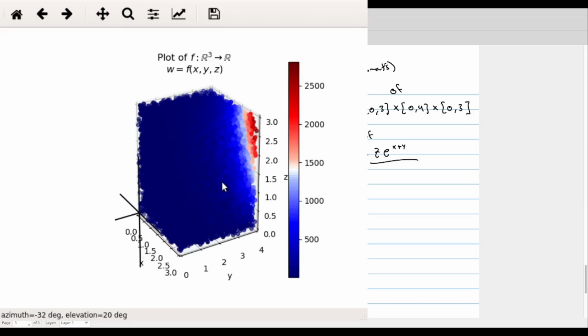If you go through and do the calculations for the centroid, I encourage you to do it. They'll end up reducing to just the very middle of this object, because you have a nice rectangle here. So the average geometric center will be the very center of this object. The center of mass will definitely not be the geometric centroid of the object, because there's more mass concentration up in the upper corner of this object.